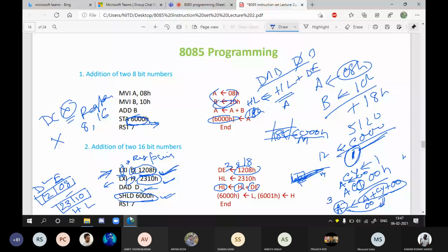So you have to write a fresh instruction. First you clear the accumulator with the help of MVI A, 00. You cannot use XRA A to clear the accumulator, because if you use it, the carry will be modified. But if you use any data transfer instruction, the carry cannot be changed. Any data transfer instruction cannot modify the flags. You remember this is the specialty of the data transfer instruction, and where you use logical and arithmetic operations and where you use data transfer instructions. It is very, very important. You keep it in mind.